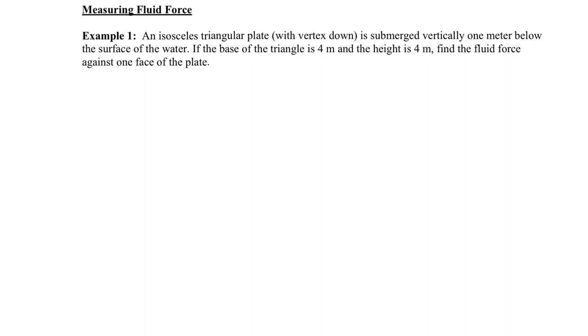Find the fluid force against one face of the plate. All right, so here's the method we're going to use. We'll draw a picture, and then we're going to consider a little sample strip on this triangular plate. We're going to figure out the force against that little sample strip, and then we're going to integrate to sum all the sample strips. So let's start off with a picture,